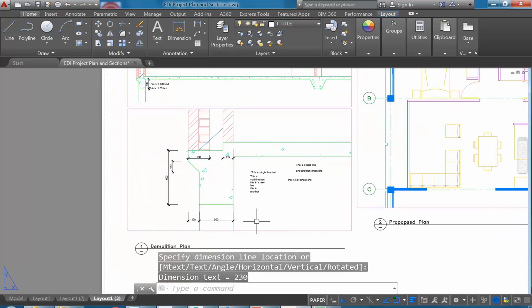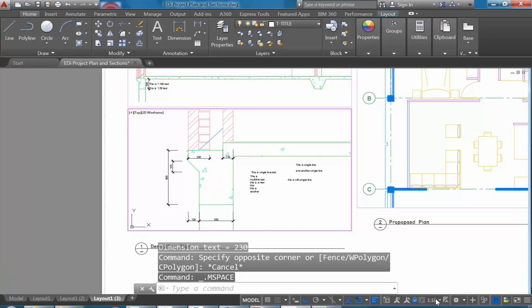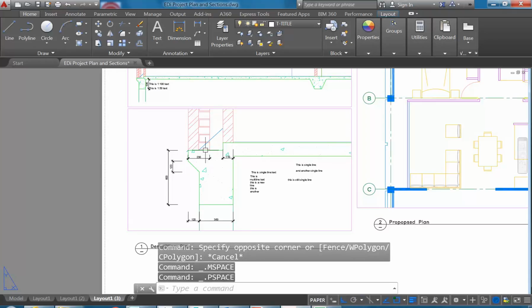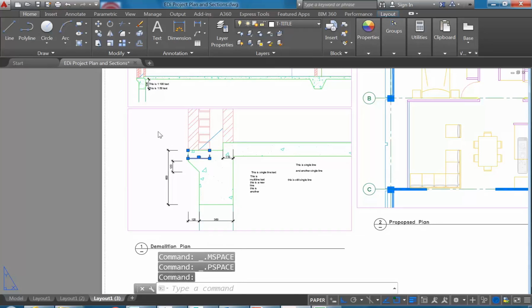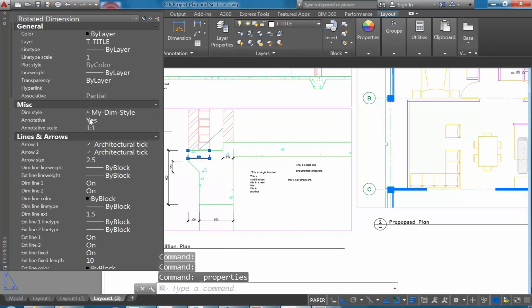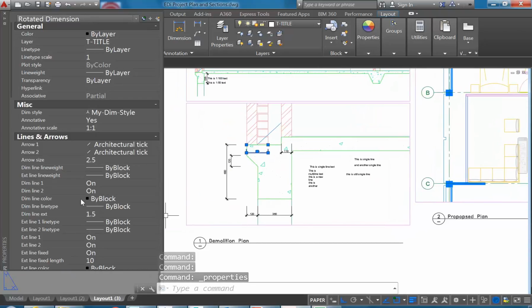There's no way that you can just look and see what the scale is. Unlike when you're drawing it in model space, you can always see the scale there. But drawing it on the page, you're relying on AutoCAD to detect the object. And you can see here, if I go into properties, it does know. It obviously knows the scale, but there's no way I can easily adjust that. It still thinks it's 1 to 1.